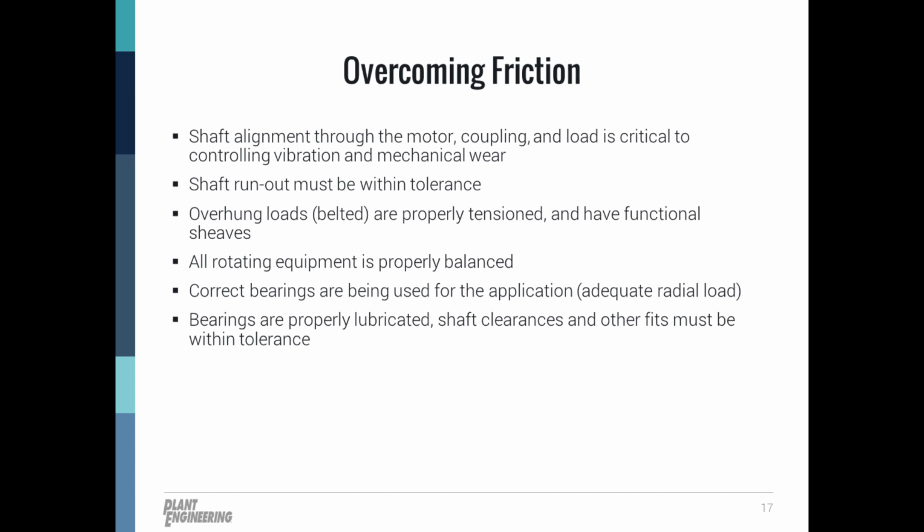So, a key factor is that the correct bearings are being used for the application. For instance, standard ball bearings would be used for direct coupled loads or lower torque belted loads. Roller bearings would be used for belted applications with the higher radial loads.